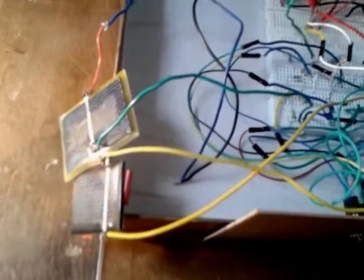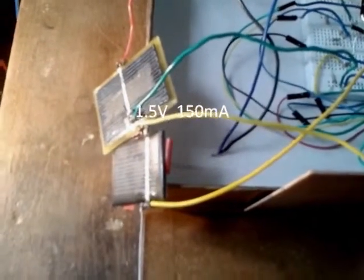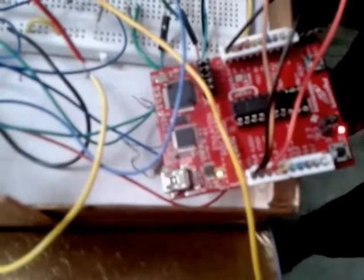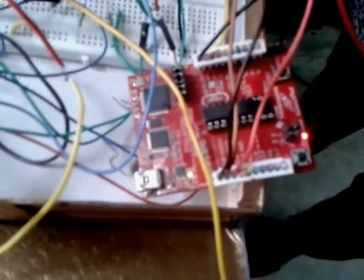Now let us move on to the working. The solar input from a PV panel is 1.5 volts 150 milliamps. We have used two panels in series. The microcontroller samples this input, performs an ADC conversion to check if the input is more than 1.2 volts, as the boost converter cannot function with less than 1.2 volts for our application.